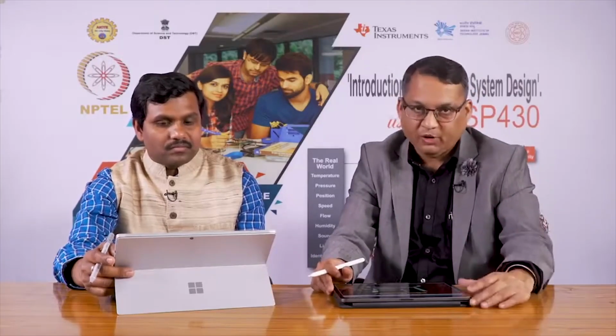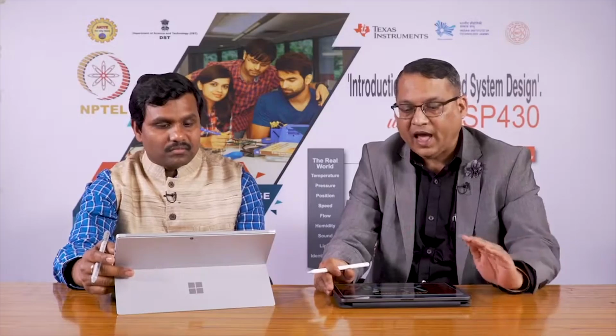Anyway, once you have the raw copper clad board and you cut it to size, the surface of the copper clad board will often be dirty and may have some scratches, and making a PCB on such a dirty surface will not result in a good quality PCB. Therefore, the first important step is to smoothen the surface and to remove all residue of oil or grease or dirt that may have accumulated.